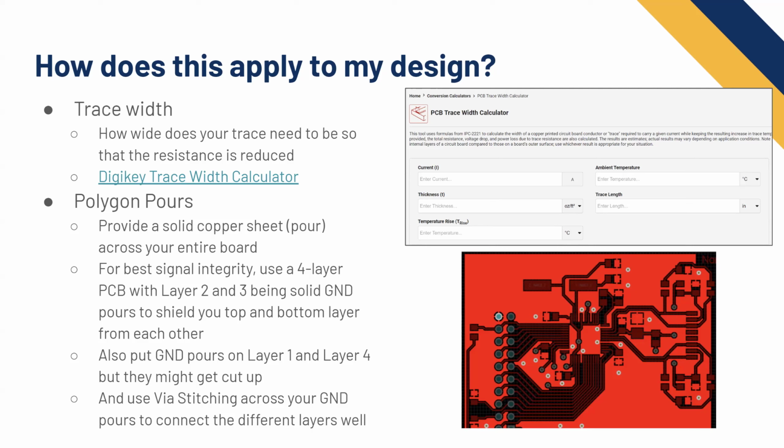This lecture didn't exactly go into how shielding works and how differential pairs work. Remember how we talked about the capacitors between the 2 nets? Imagine now if you just had a sheet of ground in between. Instead of the capacitor going from the bottom layer to the one above it, if you had 2 signals running over each other, it's now a capacitor to ground and then a capacitor from ground to the other signal. So instead of having capacitors between the top and bottom signals, you now have capacitors to ground on both sides, which is better.